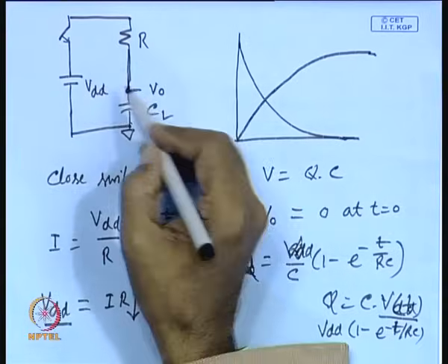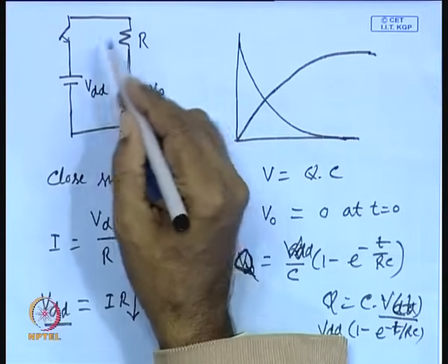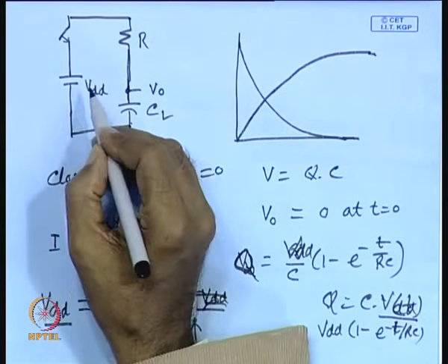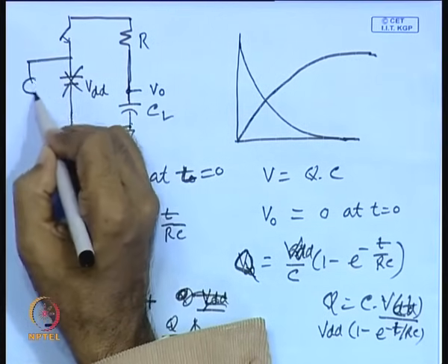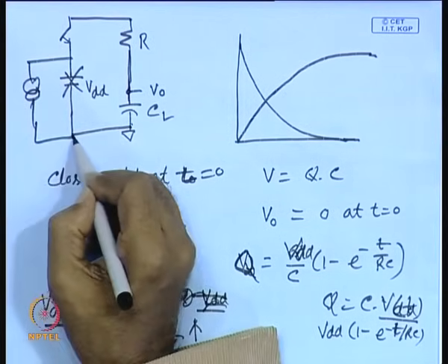Okay. So, this is how the charging occurs, but irrespective of this mechanism, we know that the energy transfer is equal to CL VDD square whenever it switches from 0 to 1, that we have seen, and the energy of CL VDD square by 2 will be lost in this resistor. Even if, instead of a voltage, we put a constant current source, even then that will take place.